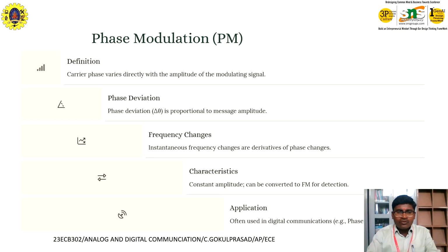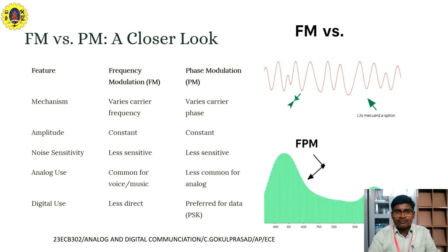Coming to phase modulation, here the carrier phase will be varied directly with the amplitude of the modulating signal. There are certain key parameters which we should focus on, such as carrier amplitude, phase deviation, as well as the different characteristics. Phase modulation plays a major role in the digital communication field.